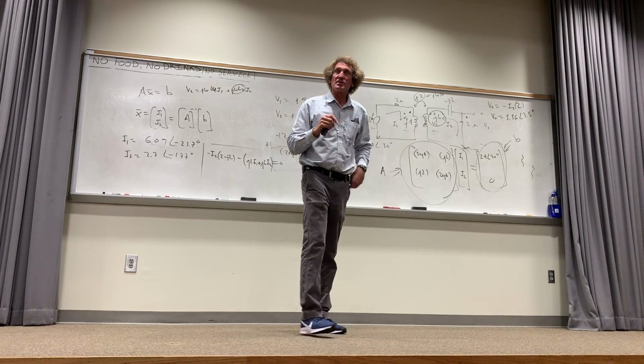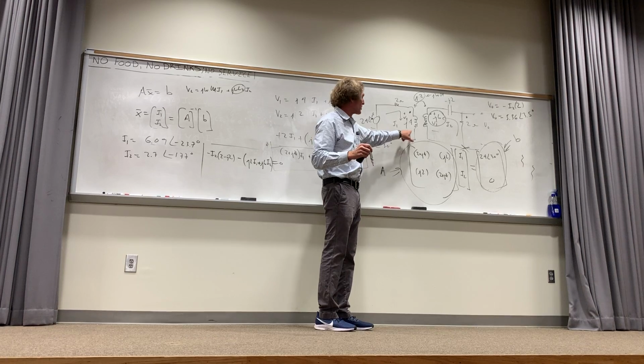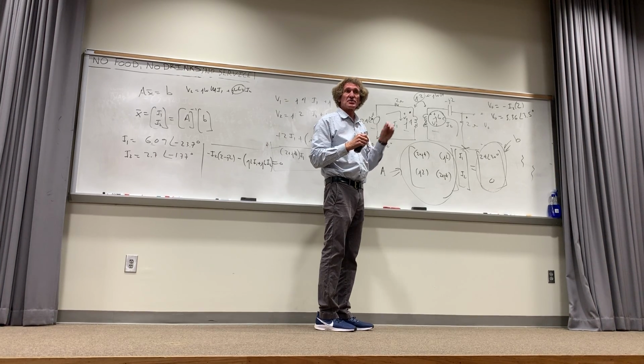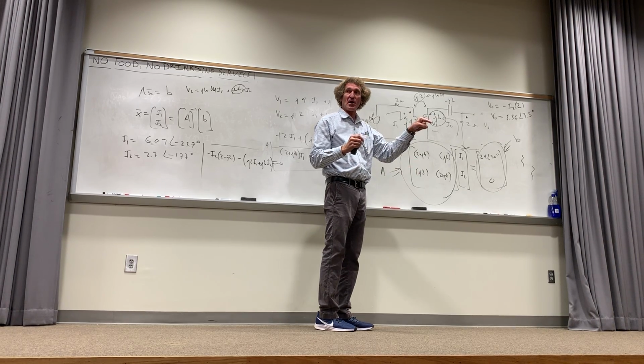And I want to tell you this because this is a typical kind of question. Well, what happens if the dot's down here? No problem. Plus, minus. All right? That's what you do. No matter however the problem looks, the plus is always at the dotted terminal. The minus is on the other side. Currents always enter the dotted terminals.